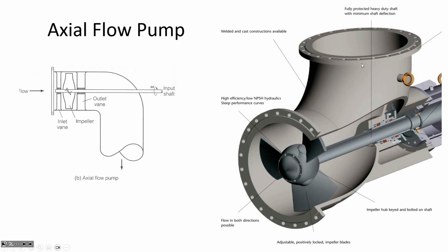the other common type of radial flow pump is if you have the impeller submerged in the pipe itself rather than in a separate pump casing. Axial flow pumps like this could be common when you're trying to lift groundwater. And so they could have the motor at the surface where it's able to be cooled and accessed if it needs maintenance, but then a shaft could be down.